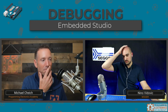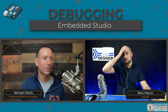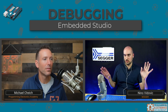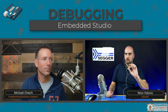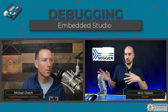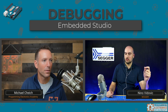Maybe one thing worth mentioning here before we switch to Embedded Studio, as mentioned, we have this universal debugger Ozone. You can also use it with the J-Link Edu Mini. You just might get the next screen, educational use only. Press OK. You have the same feature set. And then what you can do is the Arduino IDE will create this output file for the debugger to read from and to know what application to program. And the same file that Arduino IDE now is using, you can also use in Ozone.